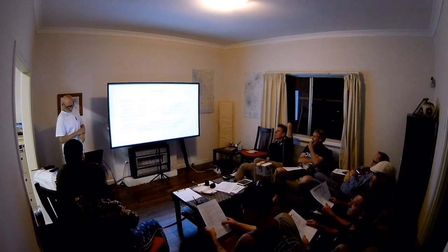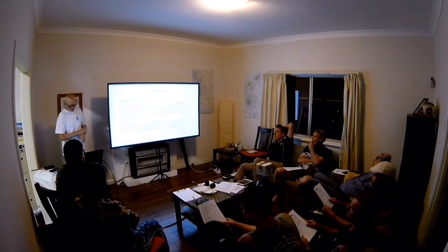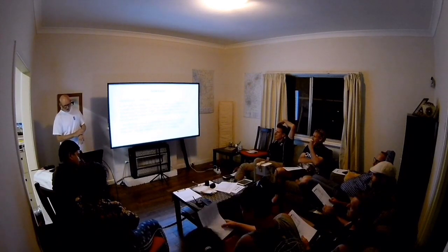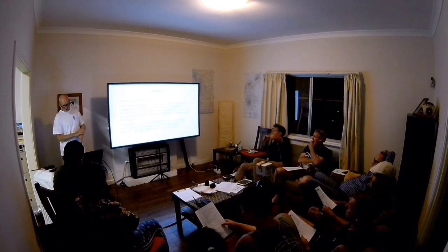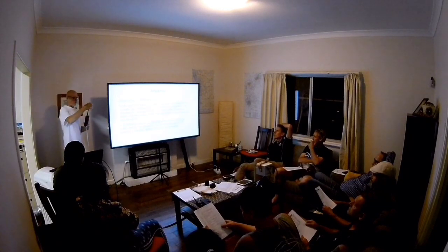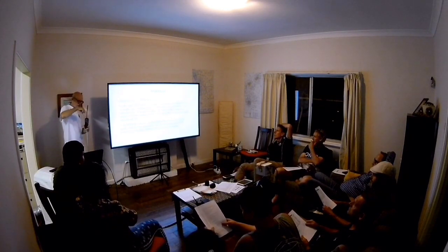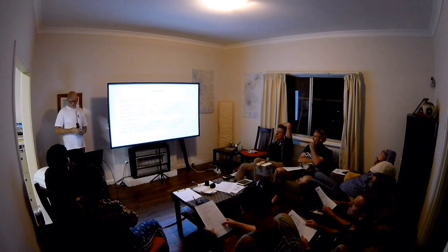Antennas. Characteristics of a VHF antenna. In a VHF radio, an antenna is a metal rod tuned to a frequency by its length. So inside our little rubber aerial here, there's actually a coil of wire which is a specific length.